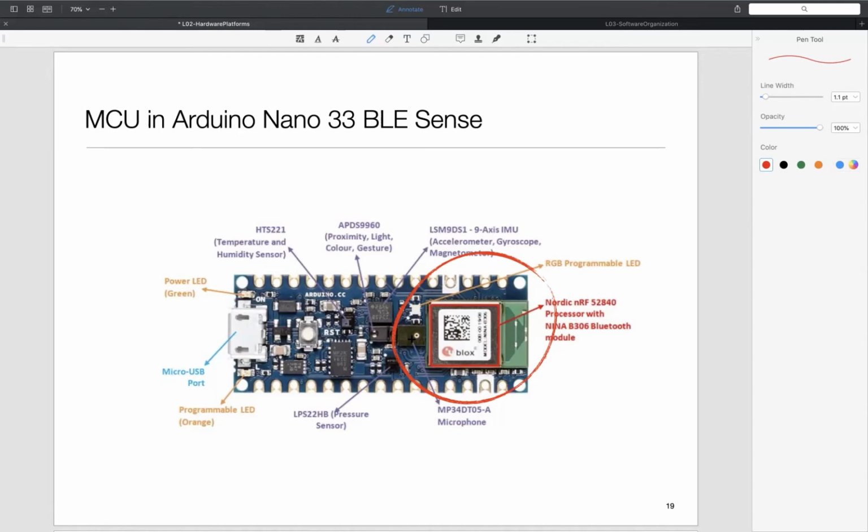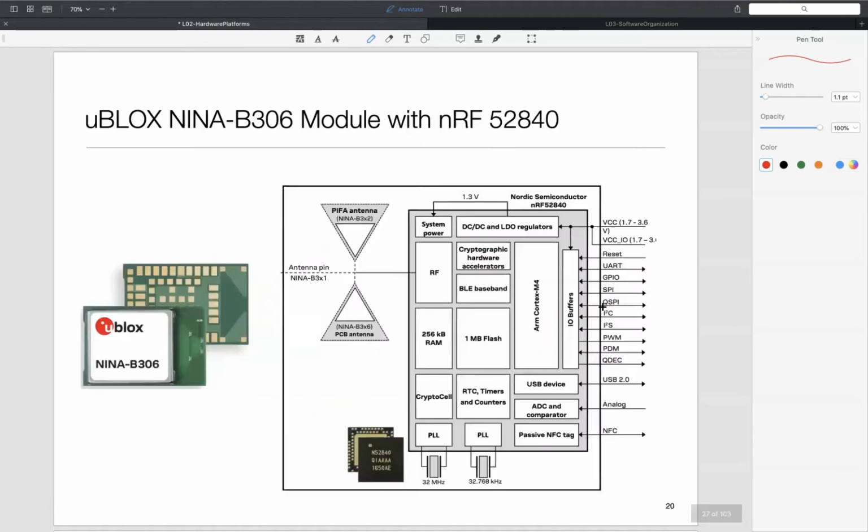And then some of the interfaces, so you see these pins along the way, and when you buy the device, it actually comes with headers that you can solder. So you can also connect a camera to it. So a lot of people kind of do things like person detection or object detection kind of things around this. The processor here is what is called a Cortex M4, which basically, think of it this way, among the microcontroller class things that come out of ARM, it's kind of at the high end. Not the highest, but pretty close to high end. So pretty powerful processor with floating point unit and all.